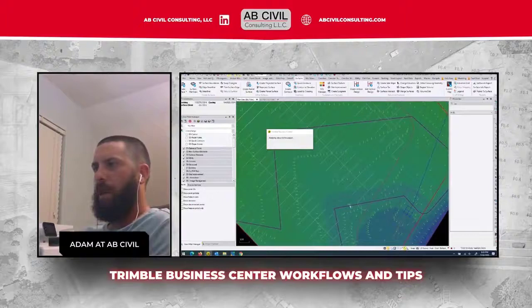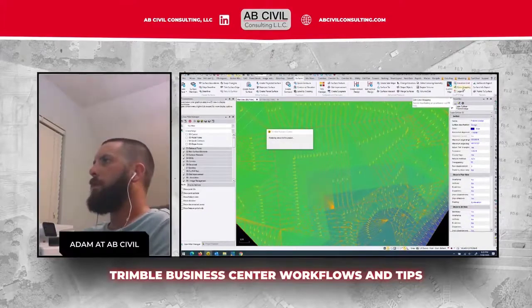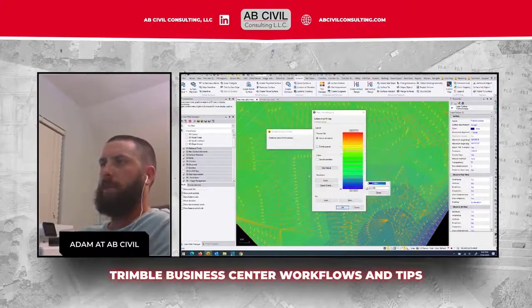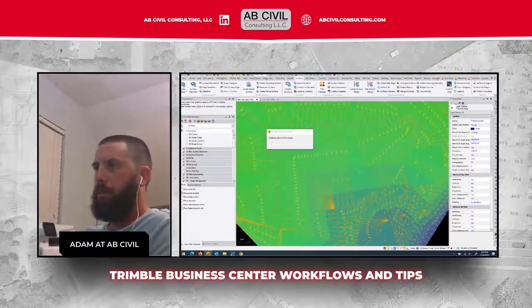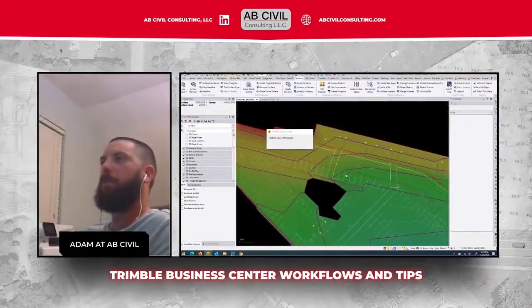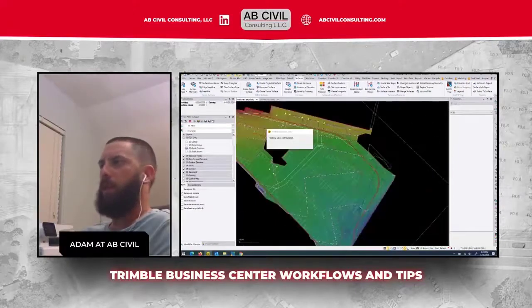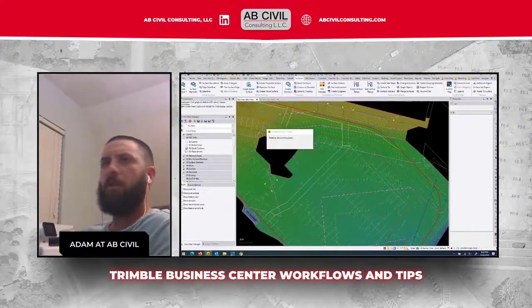And then if you click on the surface, and then under the surfaces ribbon you go over to color mapping, this is the default that was just based on the surface. If I change this to smooth transitions, you'll notice those lines went away and now it's completely smooth. This mixed with contour lines looks really good. These are the quick contours. It looks real good.